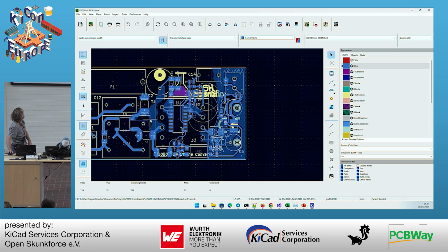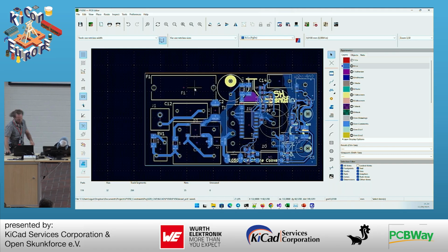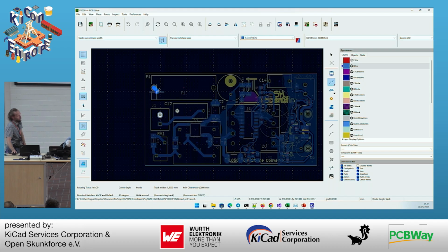Okay, this is a little tricky. Let's say we have a net up here. If you can remember the schematic, this is the fuse. And I remember that this net over here is a member of the same net class. So you can see I can actually drag very close to that net. But if I try to do the same down here, you can see it will actually keep a clearance that is different from the net down here. So now this particular net has at least 2, as you can see here. It has more, but I'm not going to get any closer to the other nets out here.